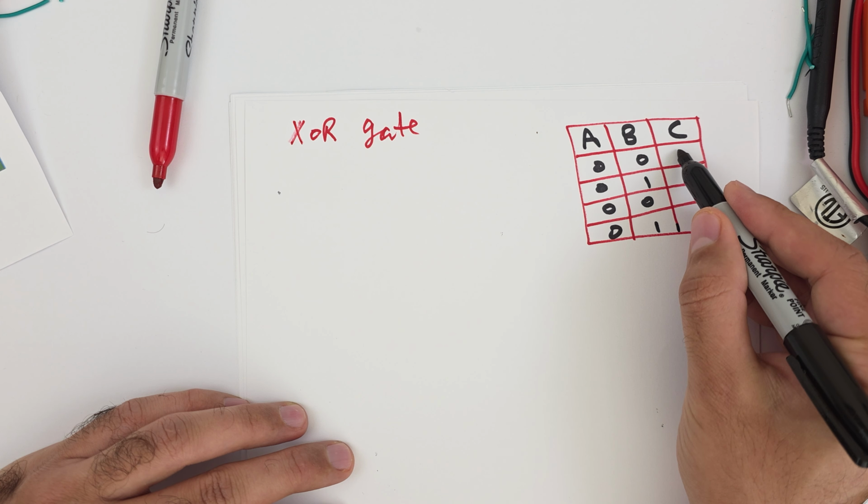Now I have two equations that we need to understand. The first equation is if we take any value, let's say x, and XOR this value with 0, what will be the result here? To understand the result, you need to use the two combinations of the x value, 0 and 1. So let's assume that here x is equal to 0. Then the value will be 0 XORed with 0, and you can see from the truth table 0, 0, 0.